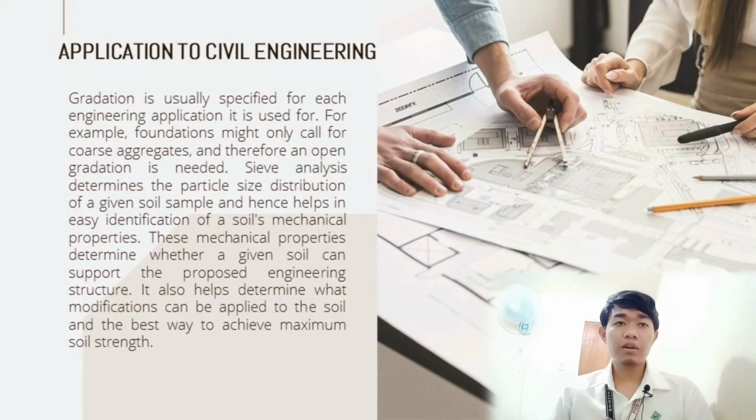And for the last topic for sieve analysis is the application to civil engineering. In here, it suggests that gradation is usually specified for each engineering application it is used for. For example, foundations might only call for coarse aggregates and therefore an open gradation is needed.